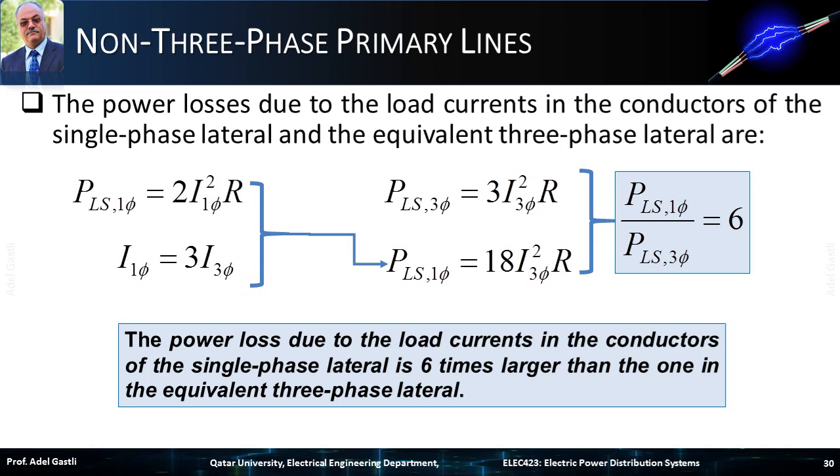It is clear that upgrading an existing single-phase distribution lateral into a three-phase lateral will increase the power transfer capability, and decrease significantly the voltage drop and power loss.